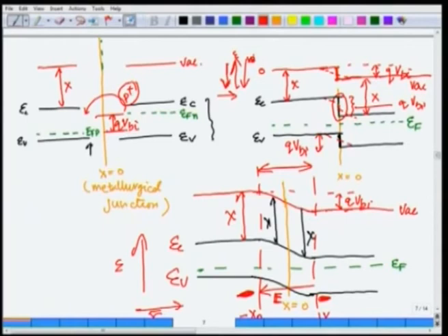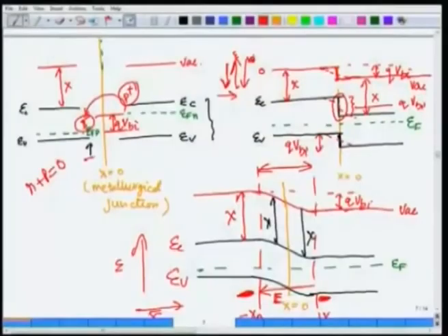And what happened? This electron which went on this side, there are a lot of holes here. This electron and hole recombined and annihilated each other. So, that led to some boron minus being left on this side. That means acceptor ionized. Remember, boron minus and a hole are neutral. The electron which came from the other side annihilated the hole, so what was left was boron minus. So, now I have negative charges lying here and positive charges lying here, then clearly electric field will set up in this direction. That is what we are seeing also in this case right here.